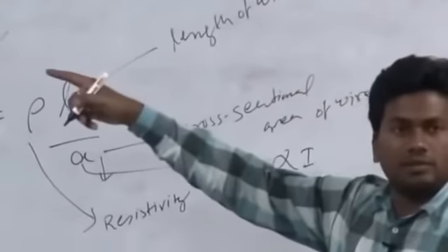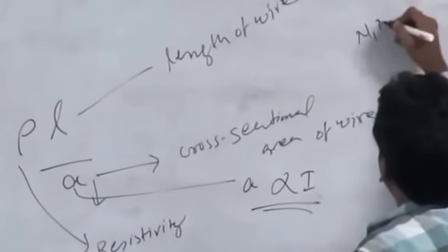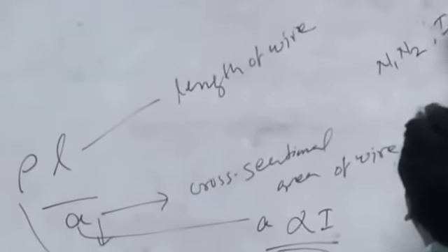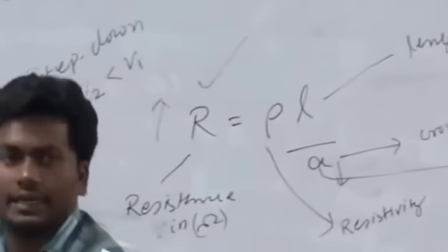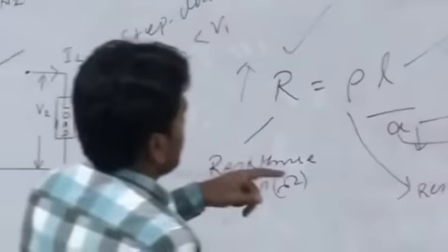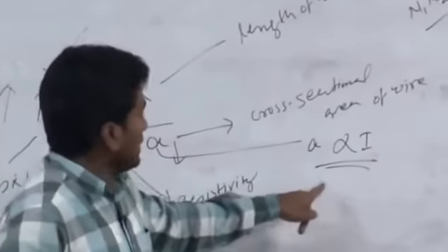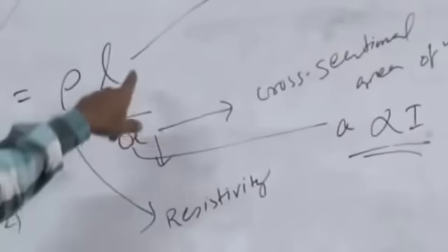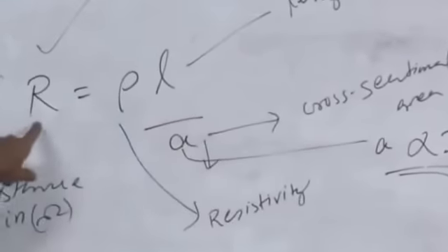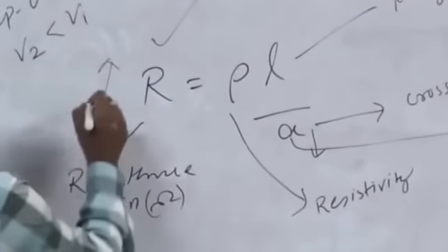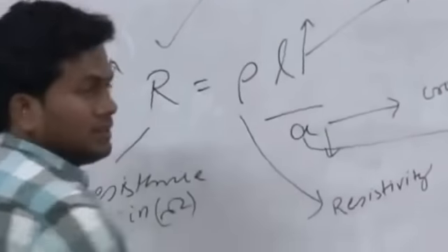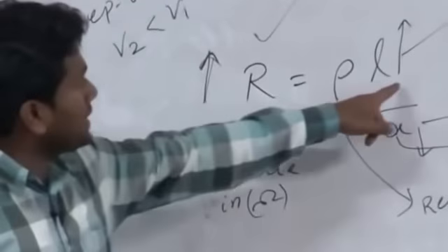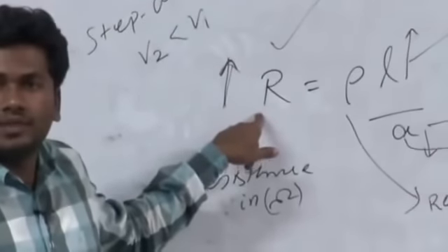Okay, so the production of MMF we have to count out here. What amount of MMF are we counting here? That is N1, N2, I1 and I2. So how the saving of copper is going to occur in the case of auto transformer, that we have to find out here. First thing is that all of you have understood how current is directly proportional to area, from this formula. Similarly, if the length of the conductor is increasing, then R is increasing, so length also increases.